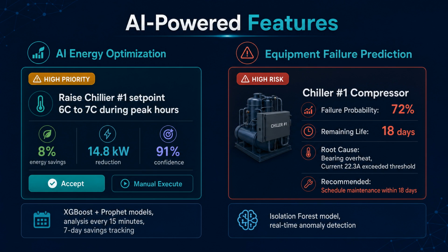The platform also supports ISO 50001 compliant operational control schedules. You can set time-based or demand threshold schedules to automatically issue control commands to your equipment. For example, you can schedule a chiller to operate from 7:30 in the morning to 7 in the evening on weekdays, with automatic shutdown on weekends.